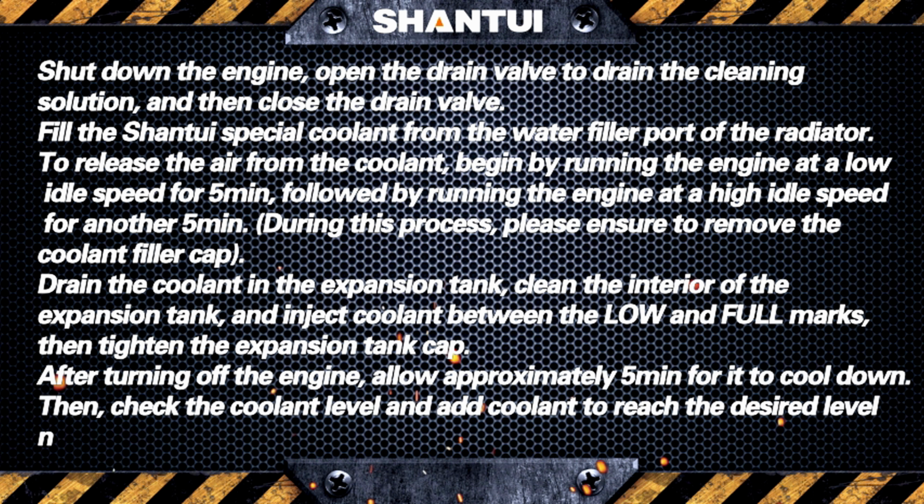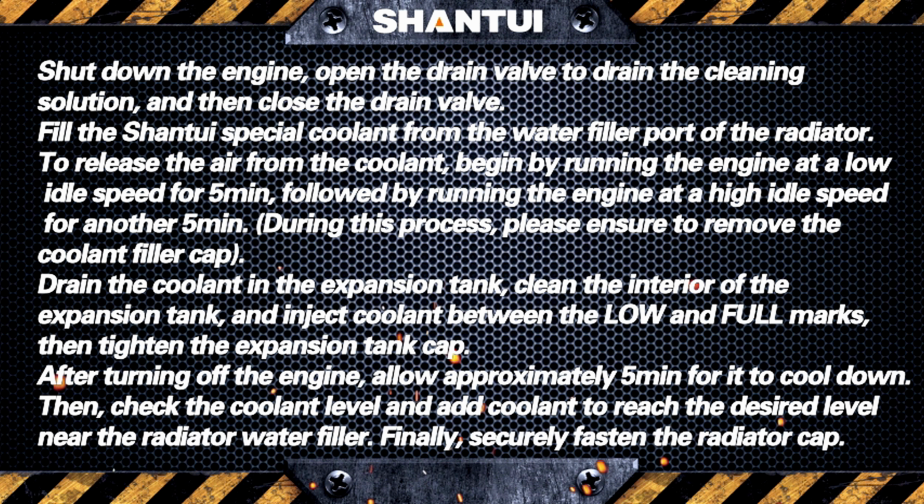11. After turning off the engine, allow approximately 5 minutes for it to cool down. Then, check the coolant level and add coolant to reach the desired level near the radiator water filler. Finally, securely fasten the radiator cap.